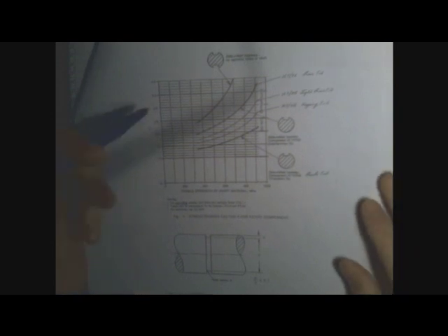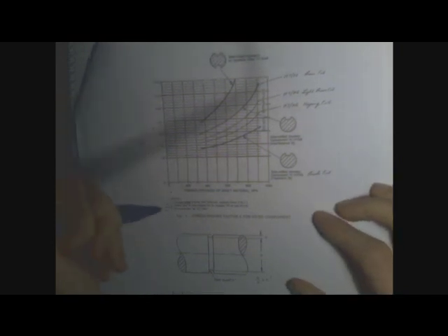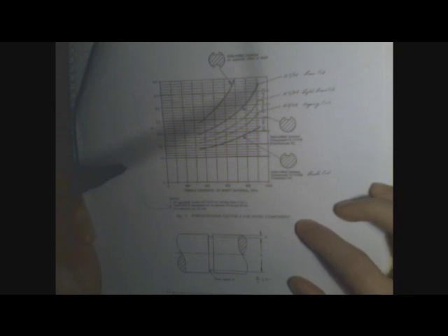And then finally I need my K value. The K value is a stress raising characteristic. Obviously we have bearings, so we're going to have to use figure 5 down the bottom of the page. You found your KS on, and then if you're putting keys in your shaft and your pulley, then you'll also need to use the one at the top over the page, figure 7.